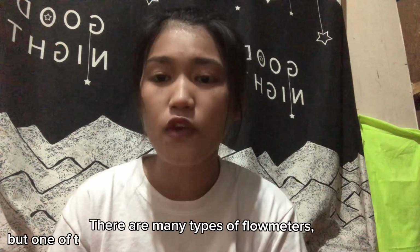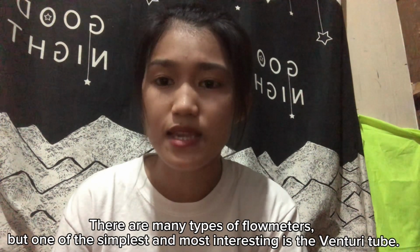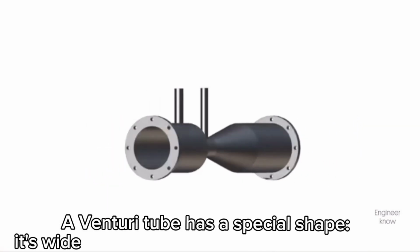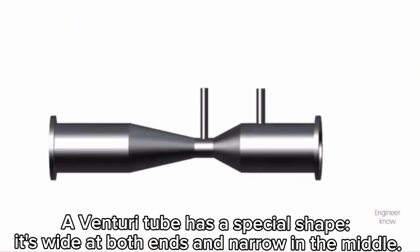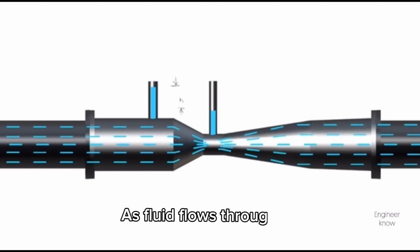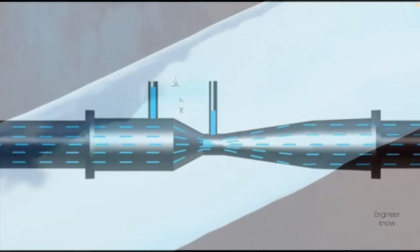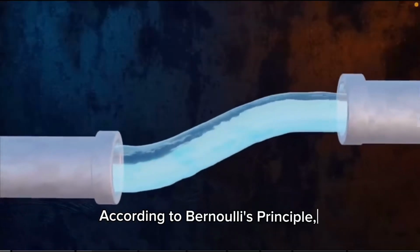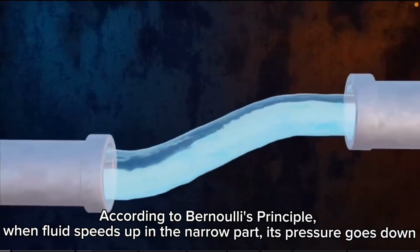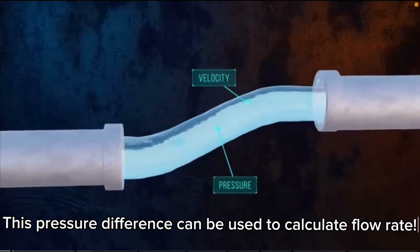There are many types, but one of the simplest and most interesting is the Venturi tube. A Venturi tube has a special shape. It's wide at both ends and narrow in the middle. As fluid flows through it, the pressure and the speed change depending on the width. According to Bernoulli's principle, when the fluid speeds up in the narrow part, its pressure goes down. This pressure difference can be used to calculate the flow rate.